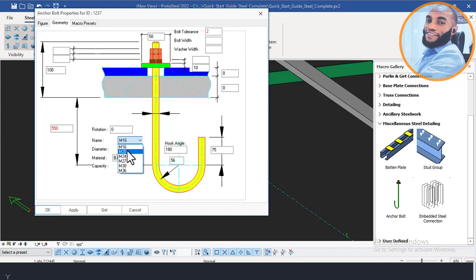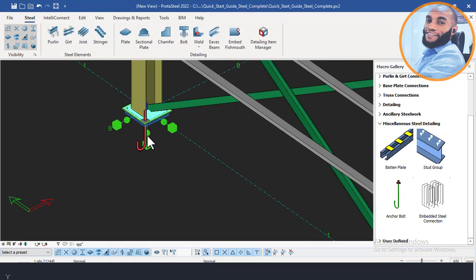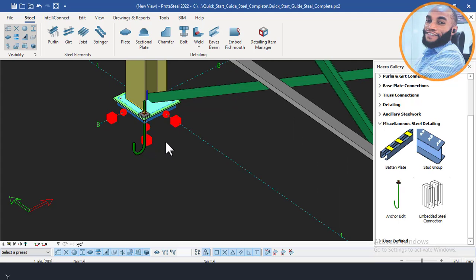Basically it was here at default as 20, so I'll come here and choose 16 here, and then choose my bolt grade here, 8.8. Okay, and I'll come here right now and then say apply, and then say okay, that's fine. So on this other place here right now.